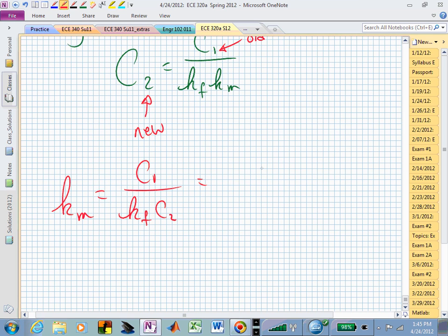Or this is now 1 over 628.3, and C sub 2 was 1 times 10 to the minus 6, so the magnitude scaling of the impedances will be 1,591.6. And I will let you use up a couple of napkins before Thursday to tell me what the circuit looks like when we meet up on Thursday.